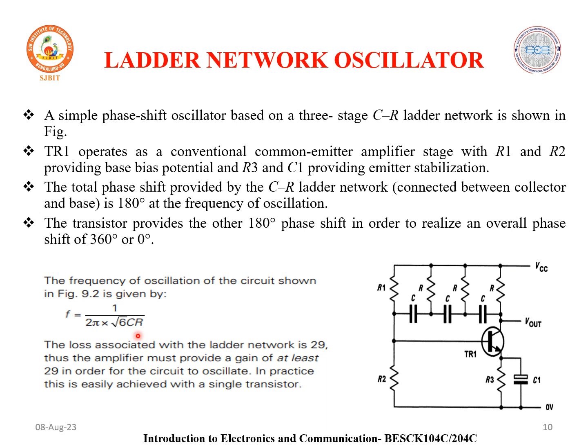When the resistor gets heated, the resistance value may change. Due to component aging also, we cannot get frequency stability. After some days, after some years, after some time, the frequency fluctuates.